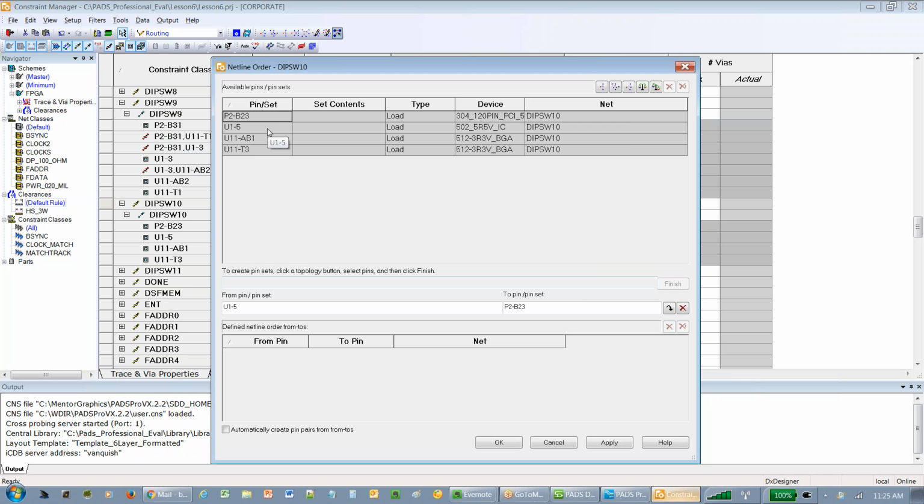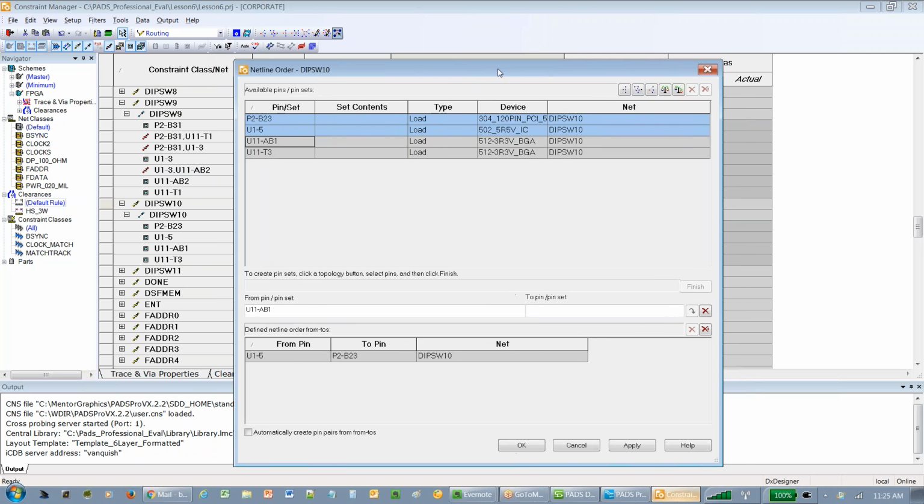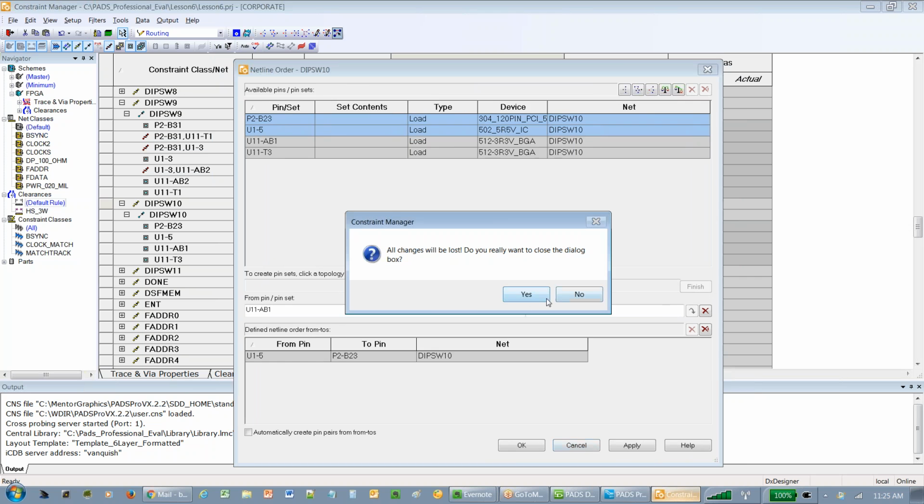This should allow me to create this pin set, but the idea here is I'm grouping several pins together into a chained, T or balanced topology, and then I can even group those 2 pin sets against each other. And what the layout tool will do for you is place what's called virtual pins, or allow the designer to move around a via location that's going to act as a pin. And now you can define length constraints between an actual component pin and a virtual pin. Again, letting you do more complex rule definition.